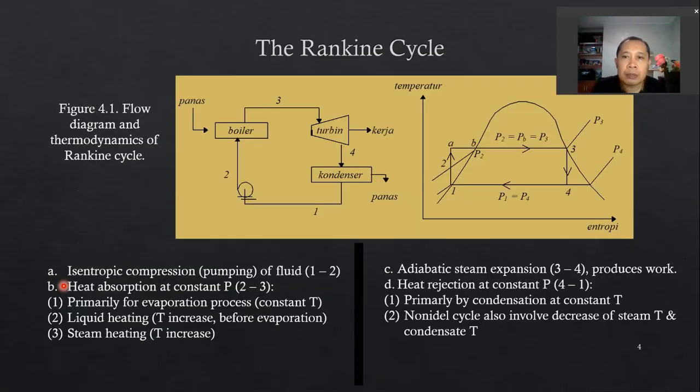So this is going back to your thermodynamic class notes. This is the Rankine cycle described on a TS diagram, temperature entropy diagram. Okay, what's happening in the Rankine cycle is first we start from this point here. We have an isentropic compression, or pumping to be exact, of the fluid. The fluid is typically all liquid here, so this would be your boiler feed water. And then the water is vaporized and also superheated in the boiler. And here, this is the turbine inlet point.